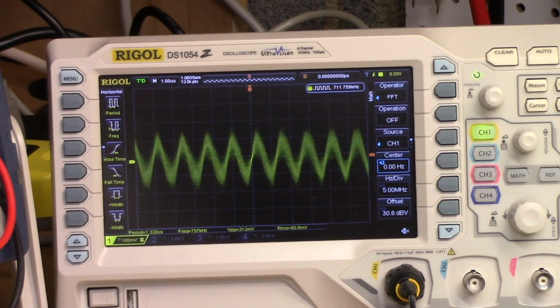And finally, here now is just a screenshot of the signal of the 780 kilohertz radio station. Got the time base fast enough that you can see the carrier wave, and what looks like noise is actually the changing amplitude, the instantaneously changing amplitude due to the audio signal that modulates the circuit.